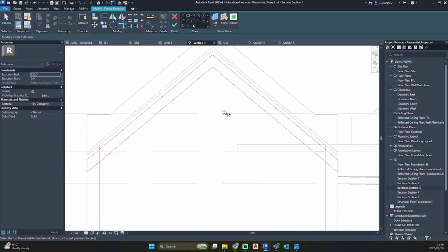So now that we have this, we need to add another stiffener in our center. So let's use our line tool just to create a center line. Let's take that down about 1 point. Let's go. Gonna draw mine in at a meter.